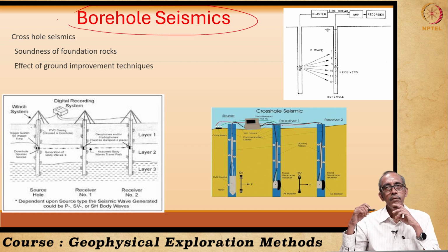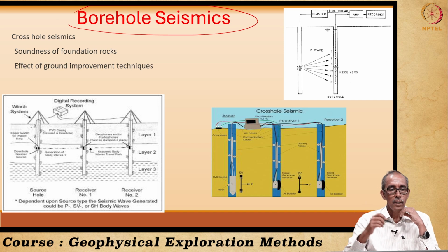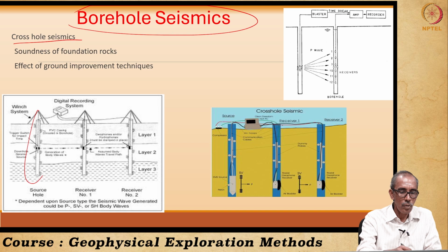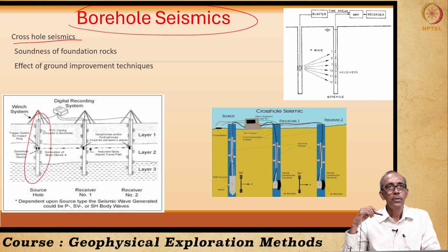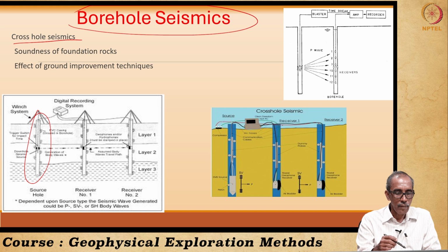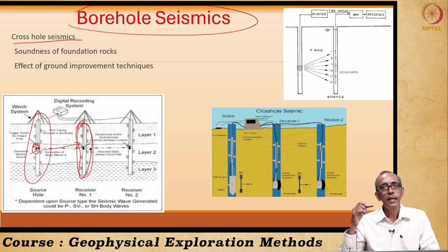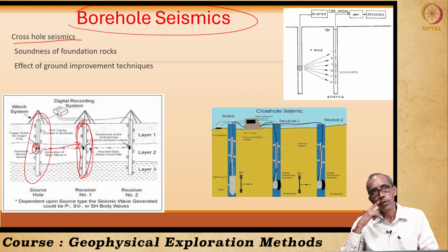That means this technique is known as cross-hole seismics. We use one of the boreholes to energize the ground. We use the source in such a borehole, and then we try to understand the impact of the energy which we have created on the adjacent boreholes by deploying what are known as geophones at different locations in the borehole.